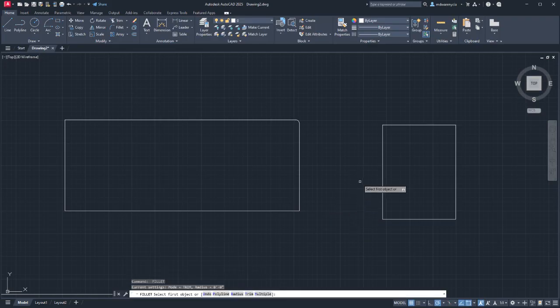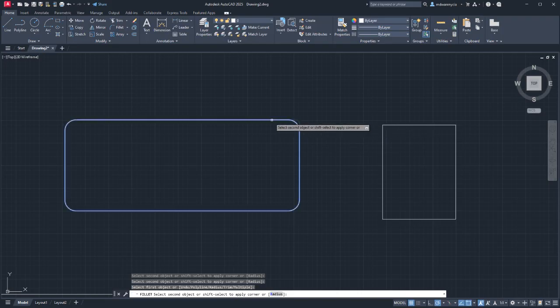Now I could hit spacebar to resume this again. Let's start our radius to 6 inches now. But we have the multiple option here. So if I hit M as well, I can jump through here, do 2 points, do 2 points. I don't think it'll let me do these two. Yeah. Oh, no, it will. There we go.